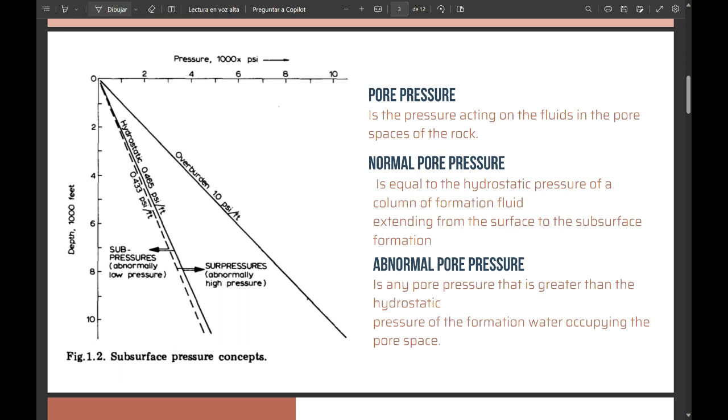Elevated pore pressure can impact the stability of the geological formation and may lead to issues such as wellbore instability in drilling operations. A normal pore pressure refers to the pressure of fluids such as water or another fluid within the pore or void space in the geological formation under normal or ambient conditions. This pressure is typically influenced by the weight of overlying rocks and sediments. So normal pore pressure is often used as a reference point for evaluating if there is an abnormal or overpressure condition.